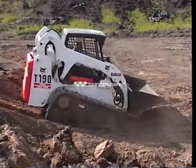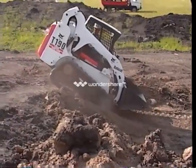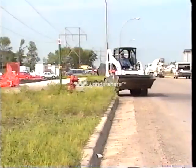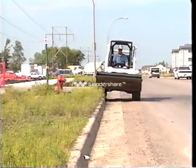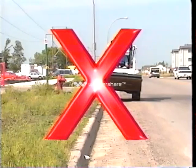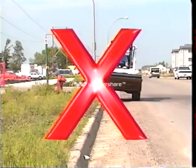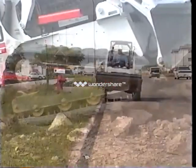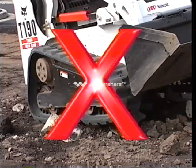And like a skid steer loader, always keep the heavy end uphill and ensure you have adequate traction to avoid sliding. Avoid operating the loader with one track on a slope and the other on level ground, or with the edge of a track turned up against a curb or mound. This can cause cracks in the edge of the tracks, cracks at the edges of the embedded metal, and possibly derail the tracks. Do not turn on sharp objects like jagged rocks or broken concrete.